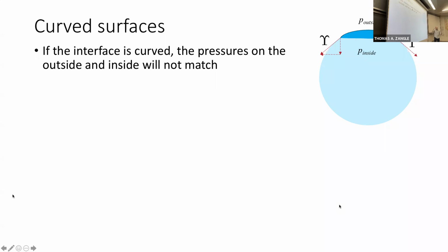So the element that I'm considering here, this is important, is going to be just this dark blue one. So we're considering just this dark blue slice of the droplet as our fluid element. The pressure from the inside, remember, always acts inwards on a fluid element. So if pressure is acting inwards on this fluid element, it's acting up, on this little dark blue slice.